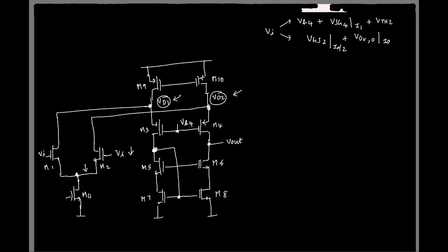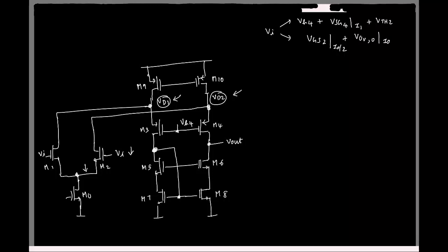Again, please remember the drain voltages of transistors don't get fixed automatically. We'll see later, if you don't do anything, we'll have to set it ourselves using some mechanism, or it needs to be set by some gate to source voltage like this, right? Because for MOSFET, the current dependence is majorly due to VGS. The current will not fix the drain to source voltage.